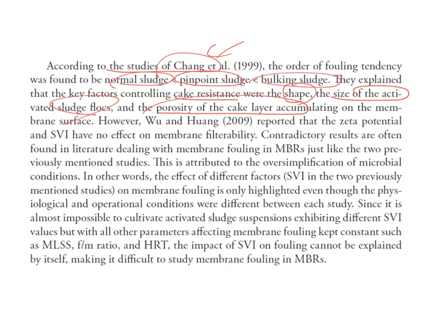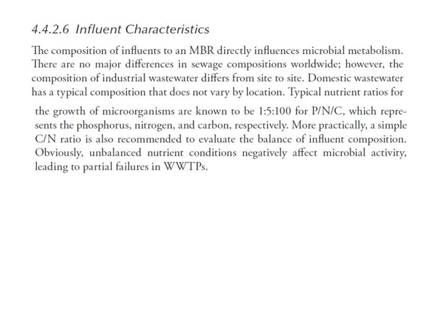So we have to consider many different factors such as MLSS, F/M ratio, HRT, and of course SVI. Influent characteristics are other factors that we have to consider in designing or operating the MBR system.